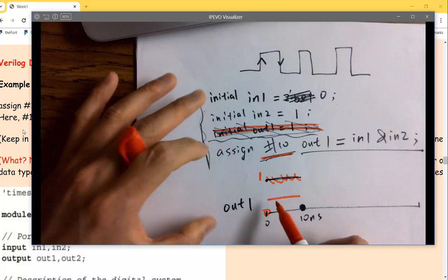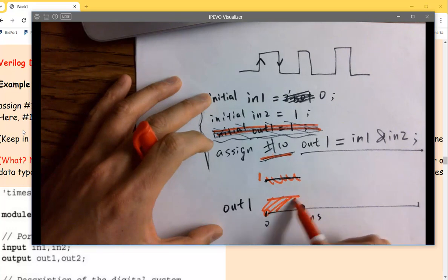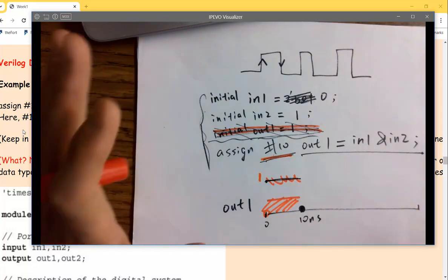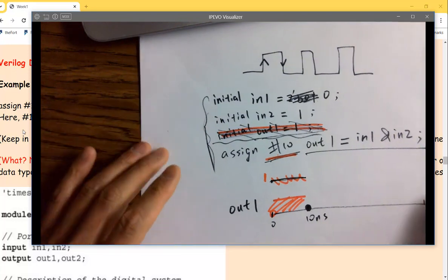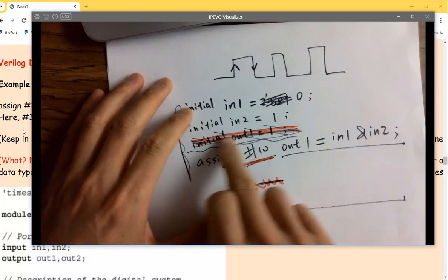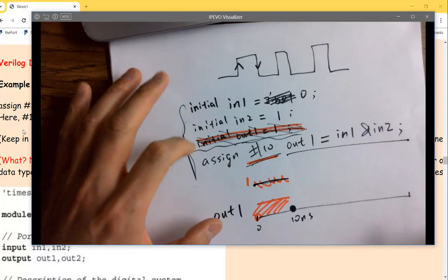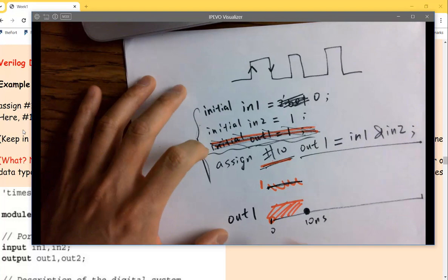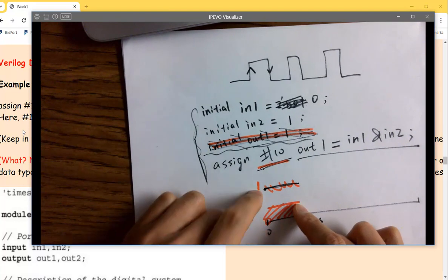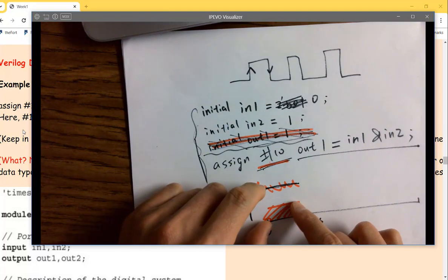It's just going to draw a green line in the middle and show a shadow, which means unknown. So to make it accurate and tell people you know what you're doing, you want to specify the initial value. But I also have an example to let you try it and show this high impedance value in the middle, so you know what that is.